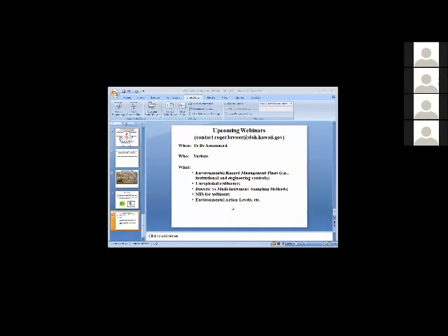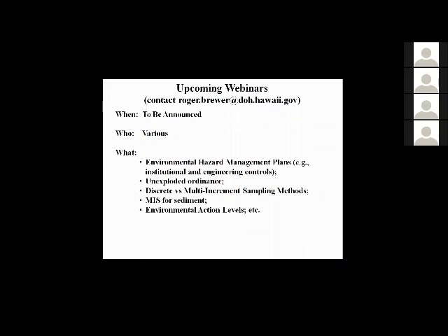And Mort, this is Roger. I ran those numbers. I assumed a 20% porosity and a fill material on the slab of 15 centimeters, and I come up with about a 25 centimeter radius of influence. Just for comparison, a 100 liter soil gas sample, say sub-slab, comes out to about a 100 centimeter radius of influence.